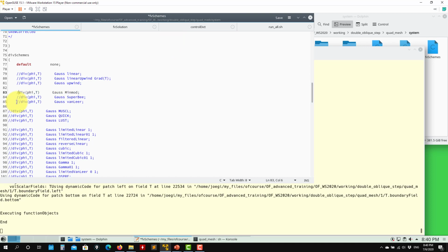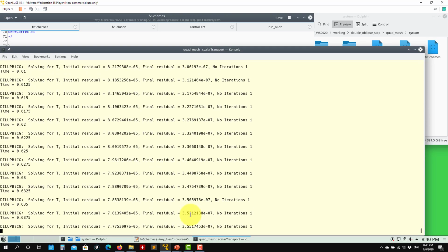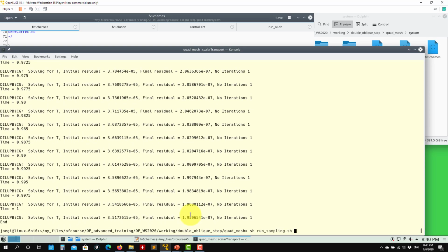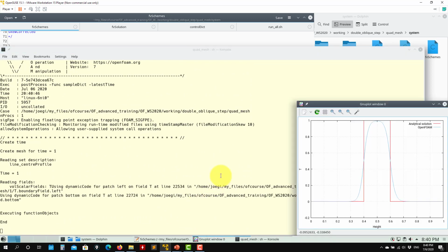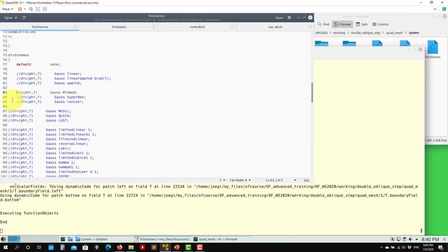I really like that method. And then we have the min-mod, that probably also is a very good choice. It's more diffusive than all the previous TVD schemes, but again, it's an accurate, very stable method. You see here, it's a little bit more sinusoidal, as you can see there. So again, just take this case, play around with everything, try to make the solver diverge or see those oscillations, just to get a feeling for how everything works.